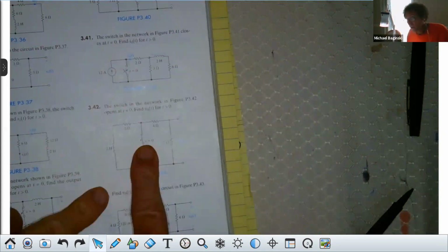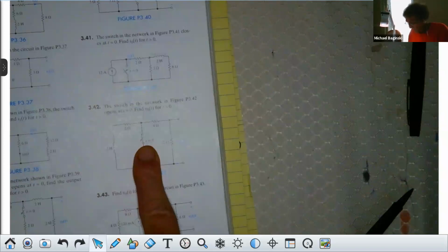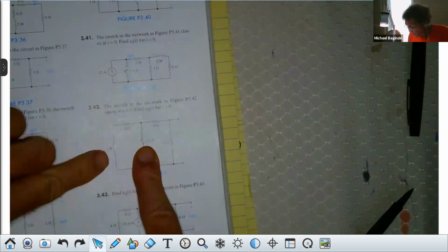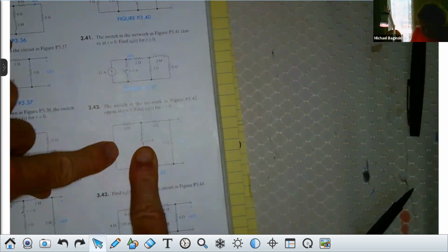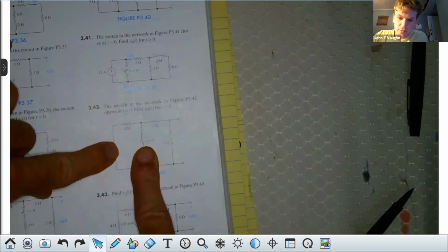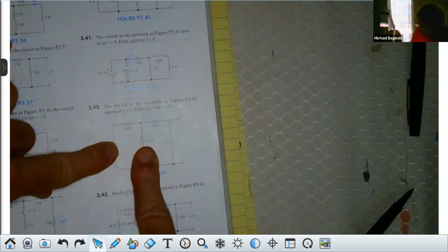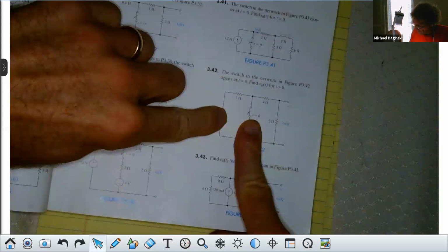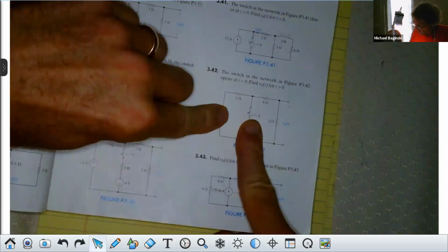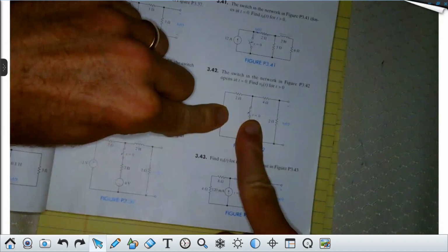Now, without doing the problem on paper, if I was to ask you what R Thevenin was, what would it be when I remove that inductor and look at the dangling leads and measure it? What would it be? Anyone? 6 ohms? Take a careful look. Would it be 2 ohms in parallel with 6 ohms? I want you to take a look at this. There's the inductor, it's taken out. What would the resistance across that inductor be? 8 ohms. How many see it's 8 ohms?